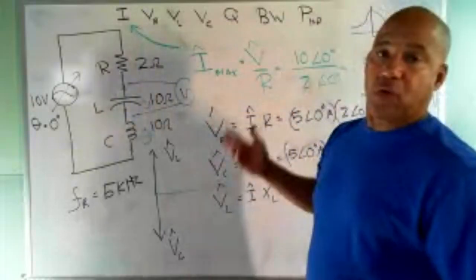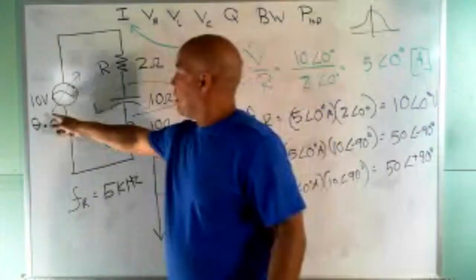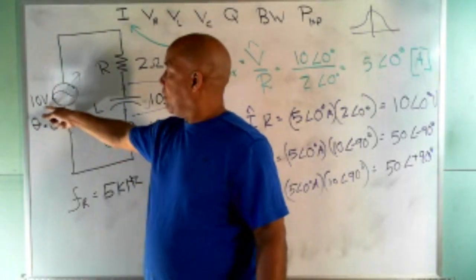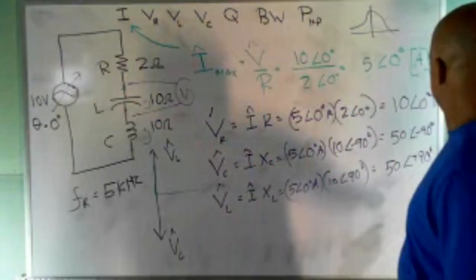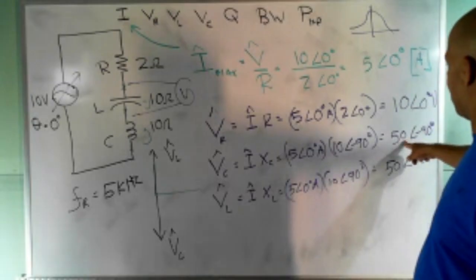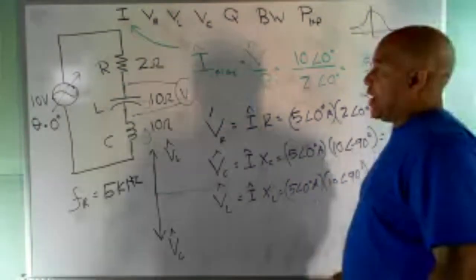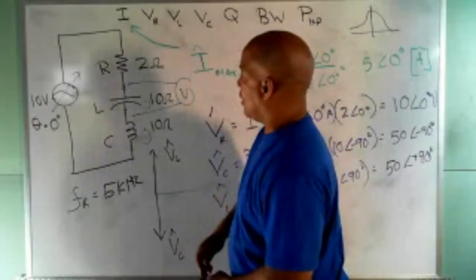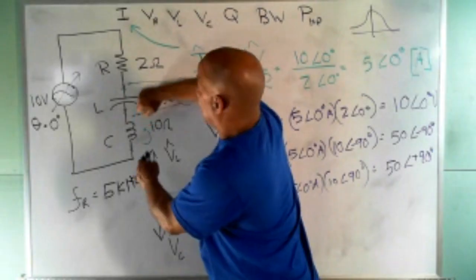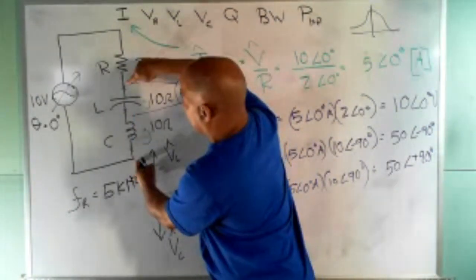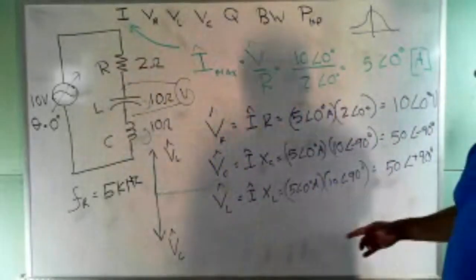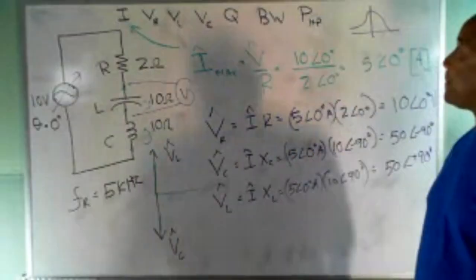Now let's say we go up by an order of magnitude. So instead of 10 volts, we got 100. So you multiply everything by 10. This would be 100 volts, and this would be 500 volts. This would be 500 volts. So if you had to grab the circuit, you don't want to do it right here, you'll cross 500 volts. But if you touch it from here to here, you'll cross 0 volts. You're safe. So you can see the canceling effect if you draw the phasor diagram.